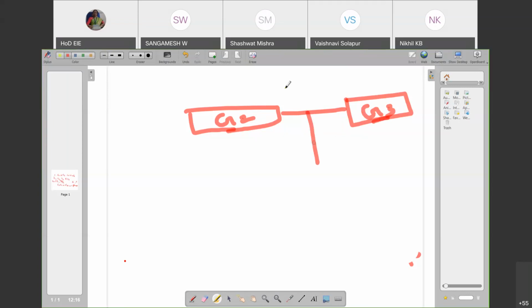So it was like this, TP1, correct? Yes, ma'am. Okay, fine. So when you look at it from the beginning, you might be having S1, S2, S3, S4. And you have a TP1 between G2 and G3. Fine. And you have TP2 after the summing element S4. That is fine. Now I know that I can make G2, G3 cascade only when I can move my TP ahead of G2. Do you agree?